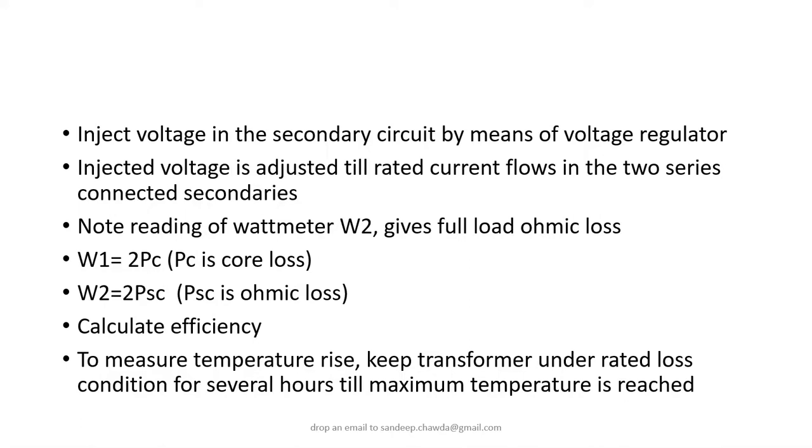And if you want to measure the temperature rise, which is the main agenda, you need to keep the transformer under rated losses condition for several hours. Why are we keeping it for several hours? So that we can find the maximum temperature the transformer can attain, since the heat is dissipated to the surroundings.